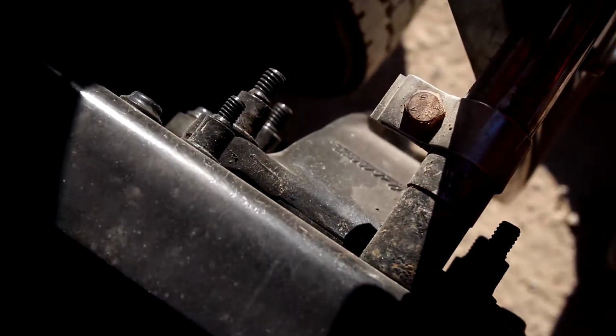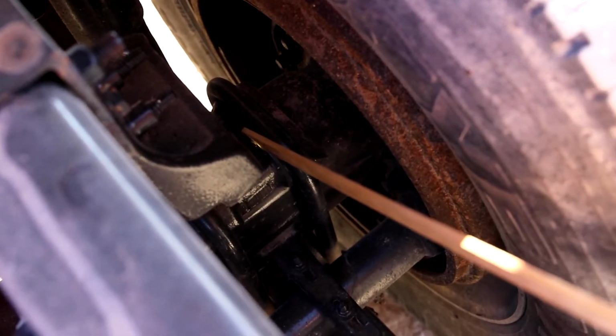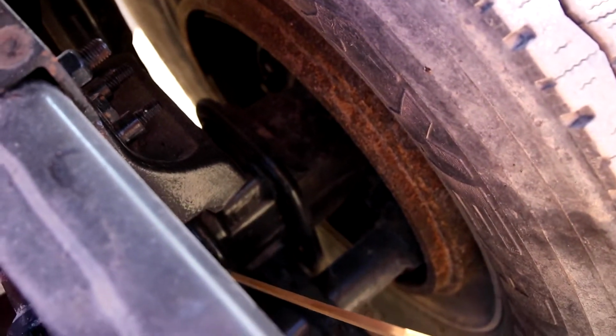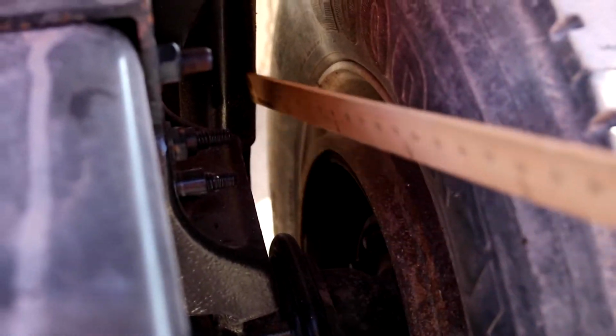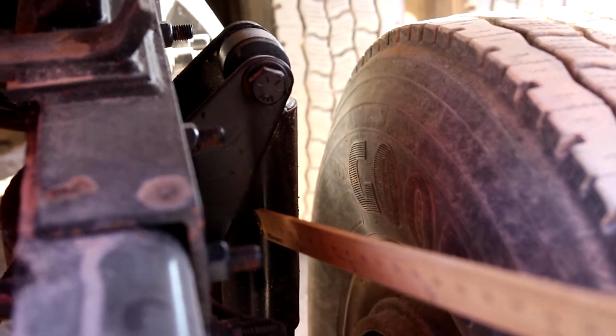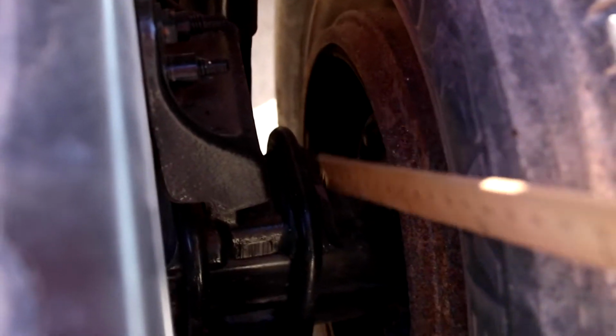This is your front spring mount. Then you have a rear spring mount. And you also have a middle mount, again, held in place with 2 U-bolts and 4 nuts. Your shock absorber is mounted securely at the top and bottom by nuts and bolts. And again, the shock absorber is filled with oil, so make sure there are no leaks.